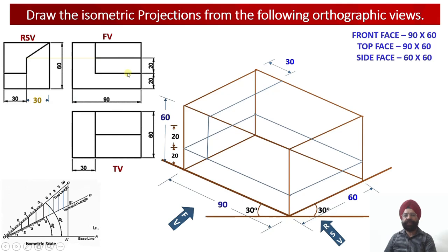This is a rectangular surface which appears as a true shape rectangle in the front view, and as a vertical edge view in the side view. Now, in order to obtain this point, I have to draw this flat surface. So a second ring has been created at a height of 20 millimeter above the first ring. Please check, this is my second ring, or the locus lines, which I have created. This ring will facilitate the location of this point of the slant surface.